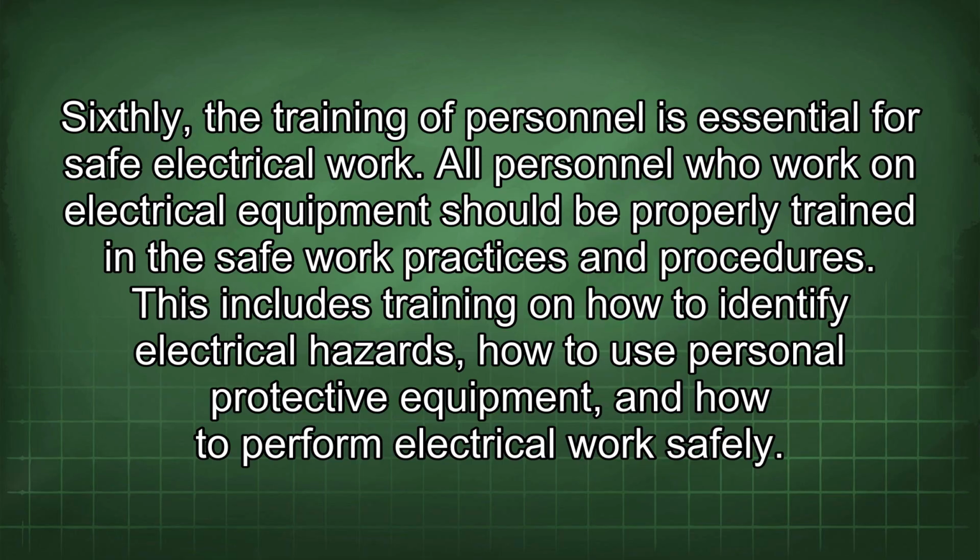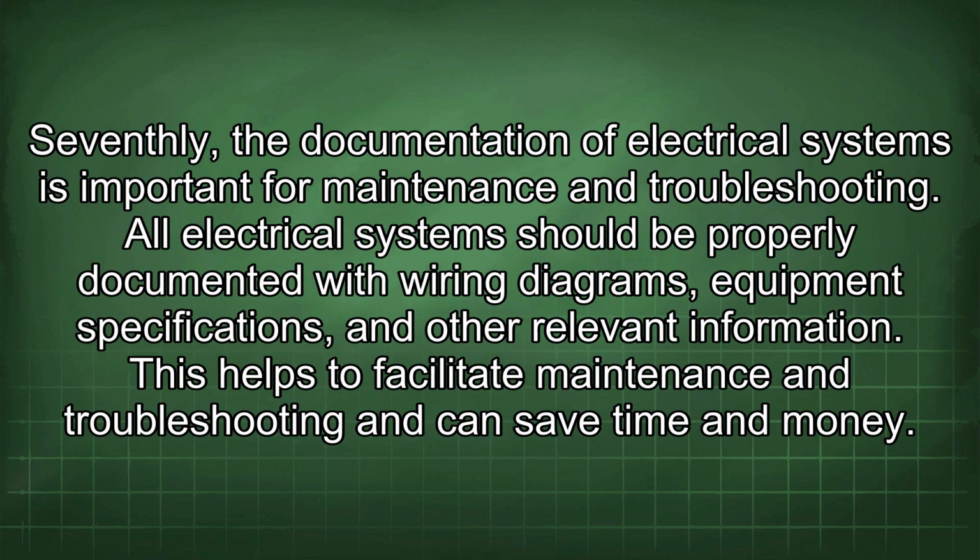Sixthly, the training of personnel is essential for safe electrical work. All personnel who work on electrical equipment should be properly trained in the safe work practices and procedures. This includes training on how to identify electrical hazards, how to use personal protective equipment, and how to perform electrical work safely. Seventhly, the documentation of electrical systems is important for maintenance and troubleshooting.